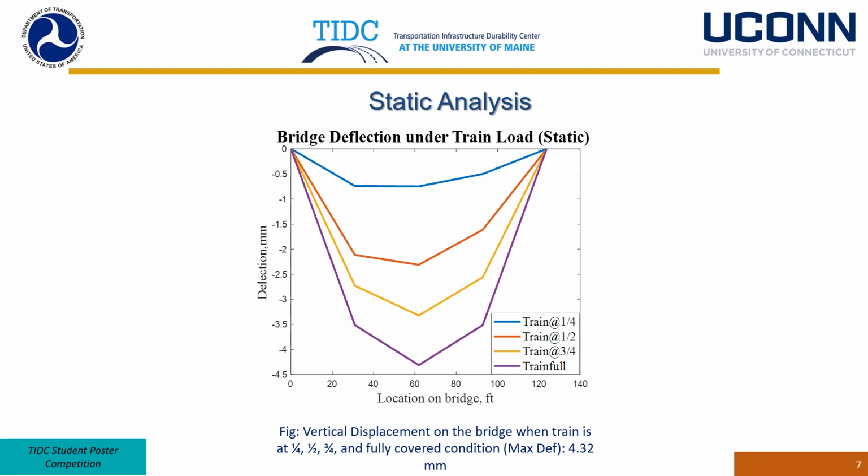Once the modal analysis was conducted, we conducted the static analysis under different train loading conditions. So this slide provides the deflection of the midpoint of the bridge versus the different train loading conditions. So when the train covers 1/4 part of the bridge, half of the bridge, 3/4 of the bridge, and when the train wholly covers the bridge.